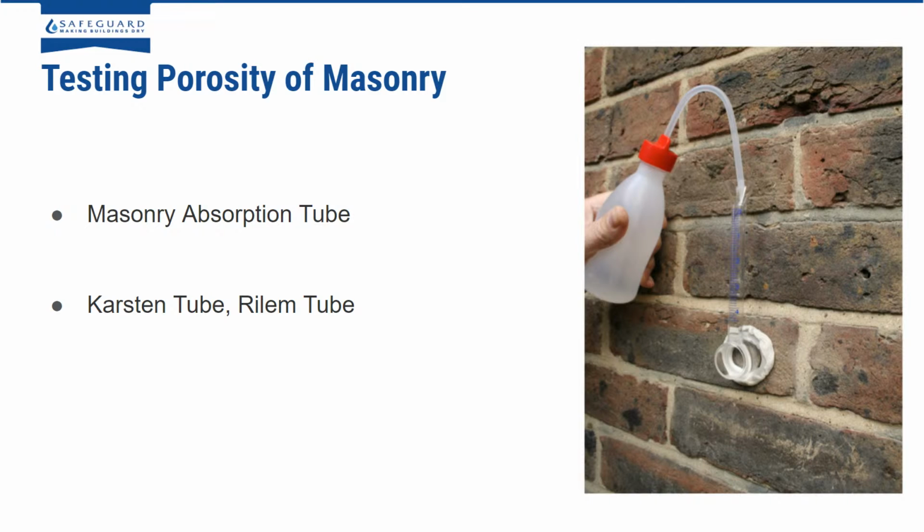Yes, exactly. And also we found, because we send out these tubes for people who want to measure the porosity of their bricks, it's very key to make sure there's no leaks through the tube when measuring. So when you are putting that little mastic tube on, make sure there's no leaks, otherwise you might get a false result.